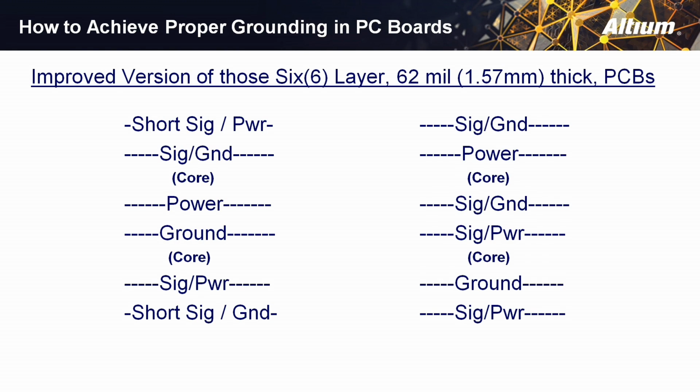So going back to the board after Lee had them redesign it, you'll notice what's happening here. There are still signals on 3 and 4, but they now are referencing, again, still the power on 2 and 5, but also there is power and ground poured on 3 and 4. So now we're not getting power from 2 and 5 only dielectric.